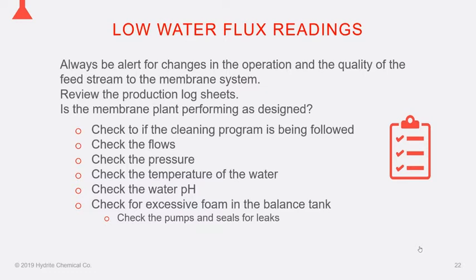And then, of course, finally, excessive foam in your balance tanks. Granted, we are using products that tend to foam a lot to clean the membranes, but if the system is designed properly with anti-foam elbows or returns back to the feed tank or to the balance tank below the solution level, foam should be kept to a minimum. If you start to see a whole bunch of foam coming out of those balance tanks during CIP, that could be an indication that you have leaky pump seals, that they're sucking air into the solution and entraining it and causing excessive foam, which is also going to greatly compromise your cleaning and lead to low water flux readings.